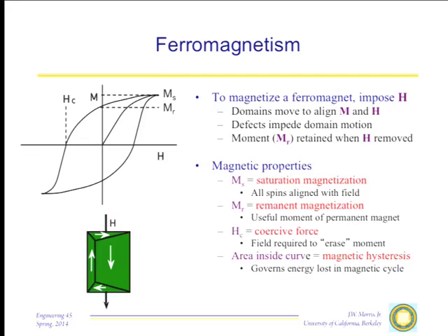In fact, the building up to the peak magnetization really has two effects ordinarily. We have to sweep the domains so that we get only one direction. The magnetic direction is usually a particular crystallographic direction. So in order to get the field aligned in the direction that we want, if that's a random direction, we also, having aligned all the axes, then have to rotate them into the proper direction. Both of these things give rise to this magnetization.